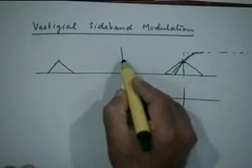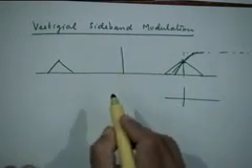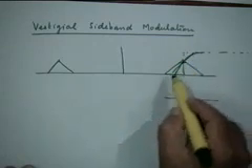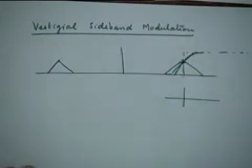So if your message signal has significant low frequency content, then SSB will create all these problems for us because of the need for sharp cutoff, which either we can't do, or if we can do it, it will be associated with these kinds of distortions. For certain kinds of signals, this is not a serious issue.